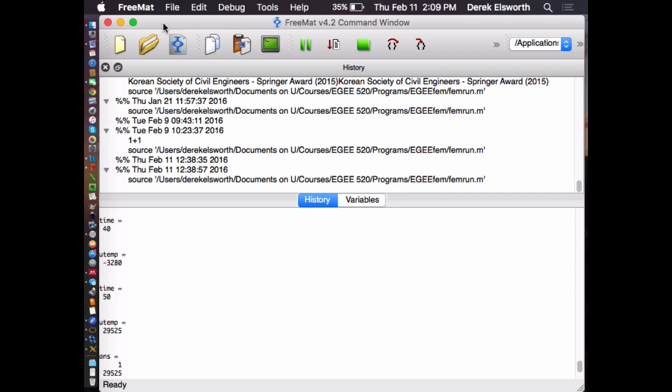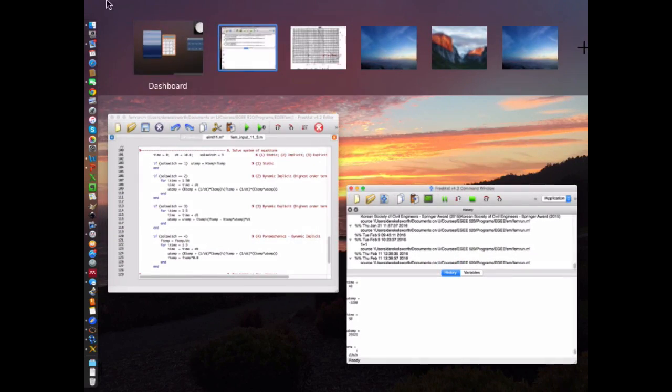We've talked about pressure diffusion, which is the fluid flow equation, Darcy's law. We've looked at how it gets localized into Q equals KH, the finite element equations for steady state, and we've taken the next step to see how we do it for transient behavior. So now we've got that taken care of.